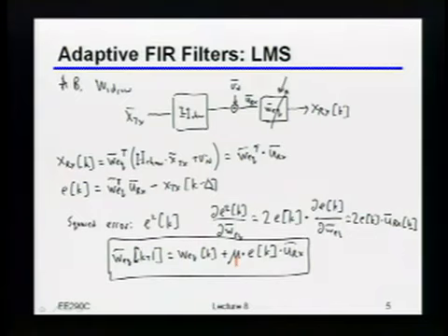Now, by the way, if you do this, what will your equalizer coefficients converge to? What type of equalizer is this? Yeah? DFE? Okay, so there were only two options, and unfortunately you got the wrong one. Turns out this is actually an MMSE. I'll come back a little later and explain why, but this converges to the MMSE solution.